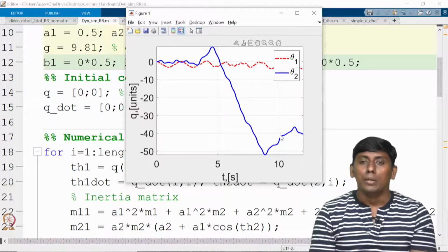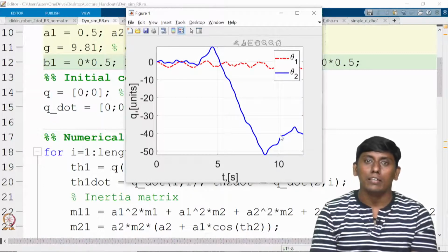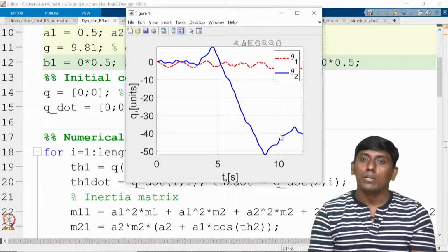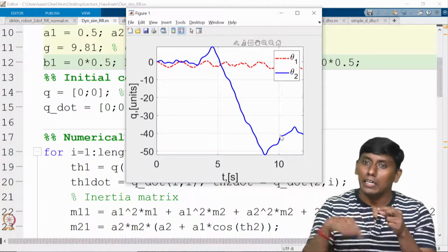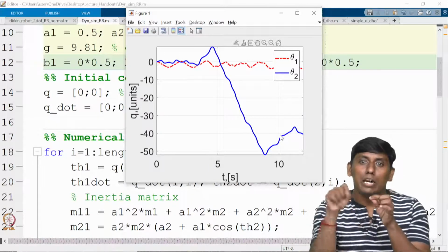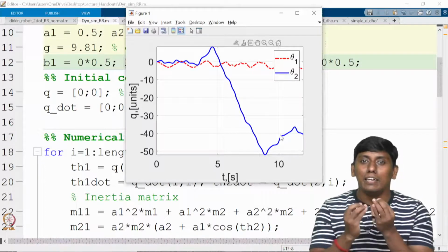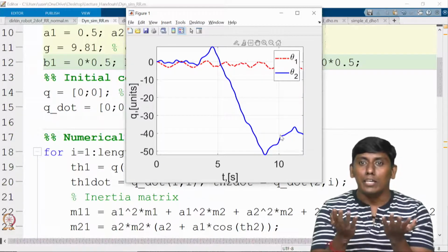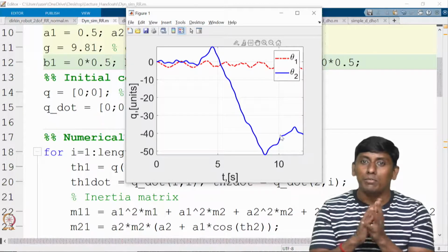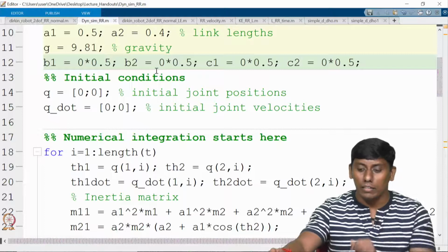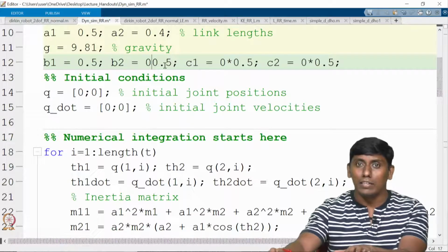It is very simple, because we have done a simple numerical integration. So this particular phenomenon is not able to be observed with a simple Euler integration. Further, there is no friction. Because of that, the second bar is making a swing up, or you can say it is producing kind of energy. Theoretically it is not justified, because as per the energy conservation principle it cannot be done this way. That's why we introduce this friction, and that way we can get more realistic results.